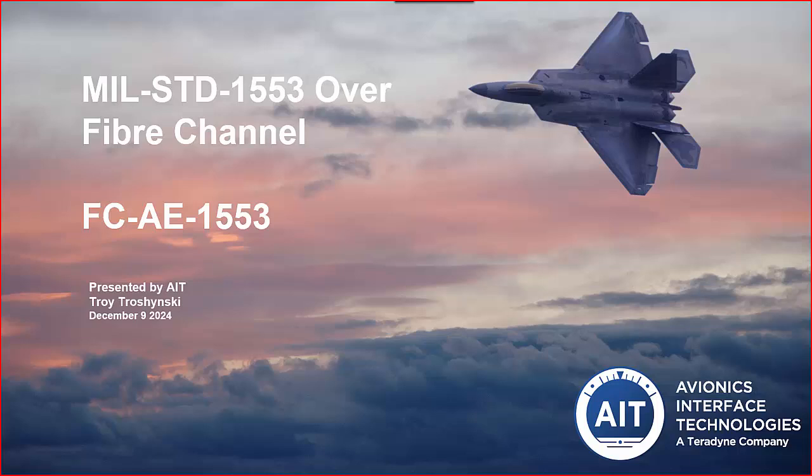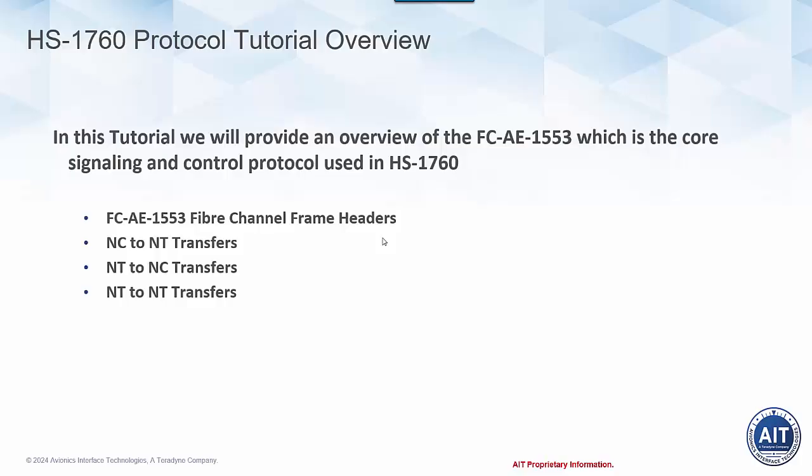Today we're going to talk about MIL standard 1553 over Fibre Channel, also known as FC-AE 1553. Again, talking about FC-AE 1553 today. What that is, it's the core signaling and control protocol used in HS 1760. So it takes the place of MIL standard 1553, which is the core signaling and control protocol of legacy MIL standard 1760 weapons bus interface.